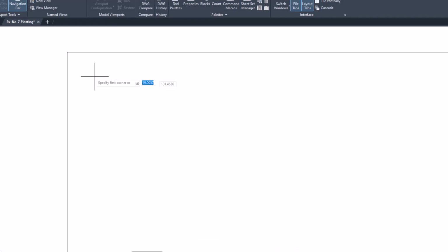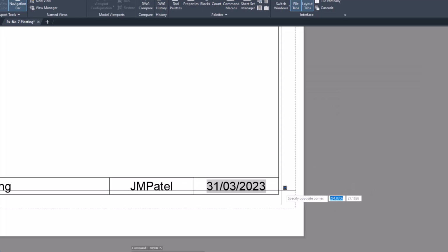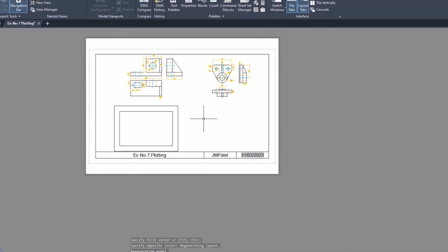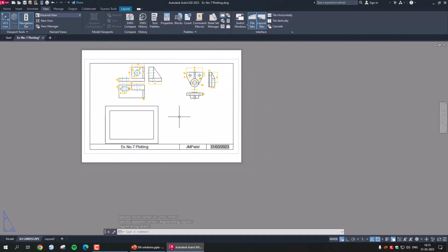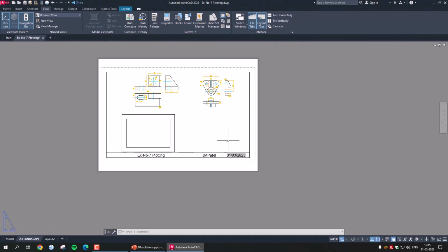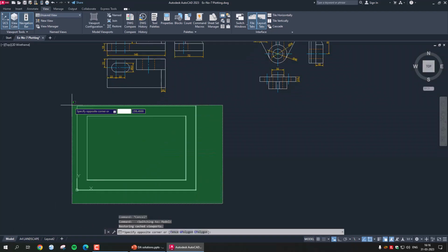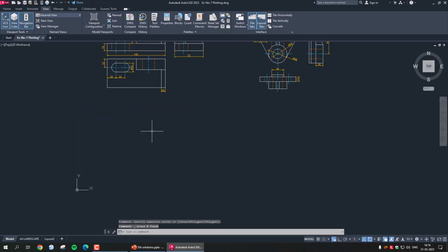Now simply go over here and up to this point. Now we are able to see the drawing. It is simply equivalent to cutting a paper and looking at what is behind the paper, right? So a viewport is simply looking at your model space drawing based on your paper size. Now I will save the drawing. I will go back and I will delete this reference drawing.